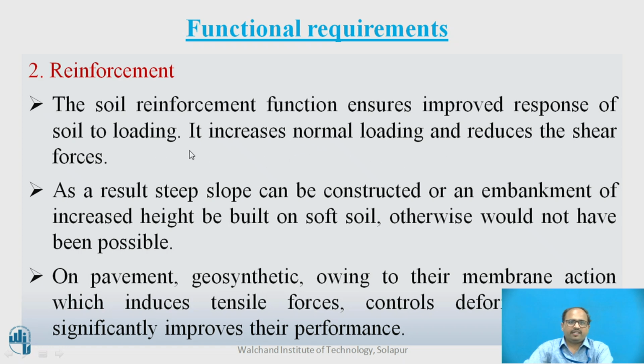Then what will happen? It increases normal loading and reduces the shear forces. As a result, steep slopes can be constructed, or an embankment of increased height can be built on soft soil, which otherwise would not have been possible. On pavements, geosynthetics, owing to their membrane action which induces tensile forces, control deformation and significantly improve performance.